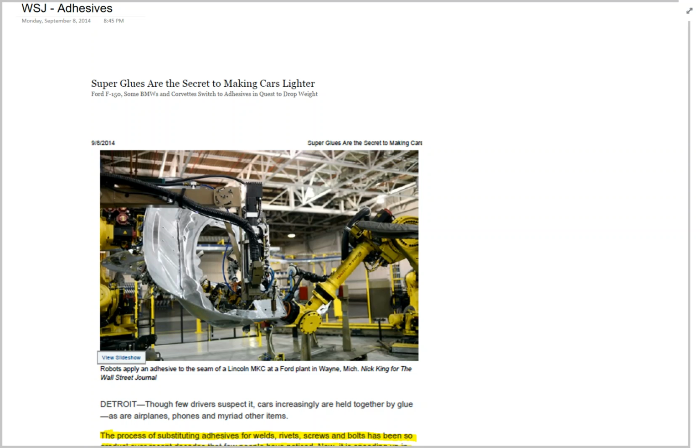And even in some of the aluminum planes, they're using adhesives over rivets. And there are some significant advantages to that. What do you suppose some of them might be? Rivets traditionally were used to put airplanes together. There were literally millions of rivets in some of the older versions of the 737. And now a large amount of that has been replaced with adhesive.